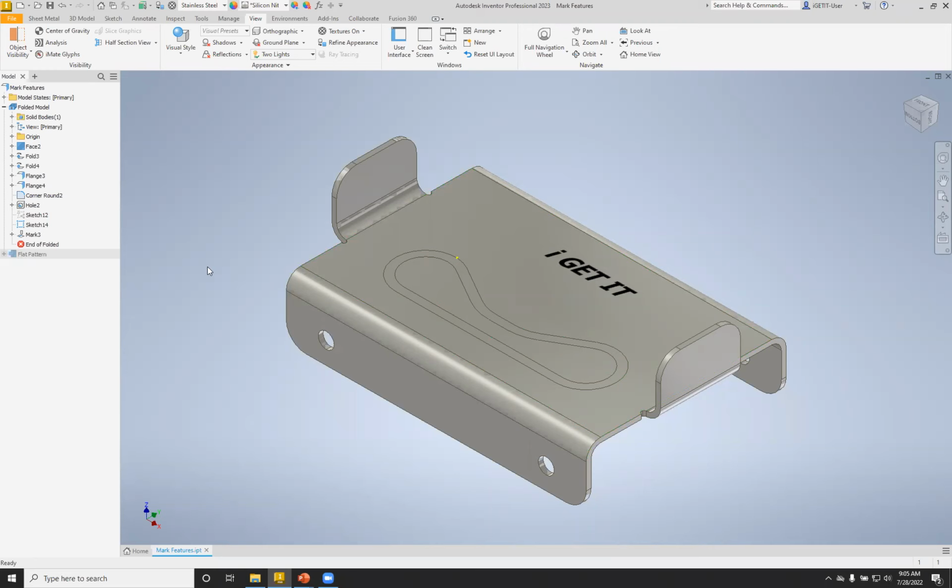Maybe it's just something that's getting painted on, or something that's getting etched on. So it's not really adding or removing material. There were a couple of ways you could do that. You could create some geometry, like an extrusion of 0.00001, so it's barely anything, so it would represent this. Or you would have to do an operation where you create some geometry to split this face. With this command, it just quickly creates that split in that face automatically.